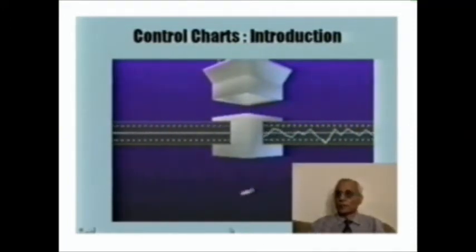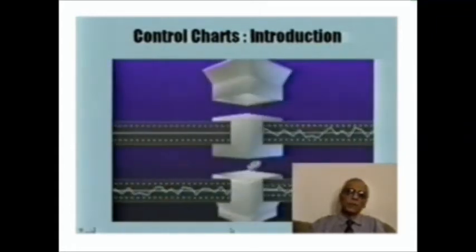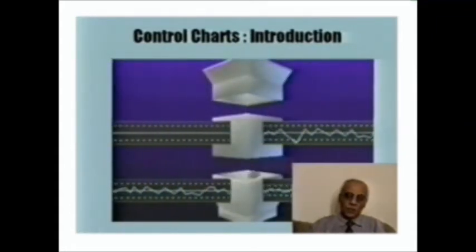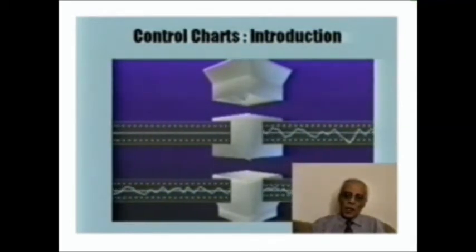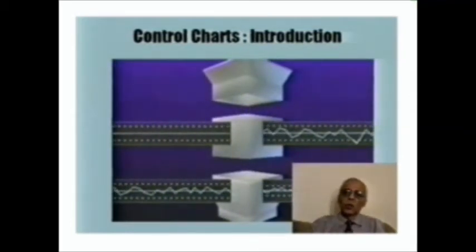A control chart concept simply means collection of data on a daily basis and determining what we call the data statistics, or the average of every day, or the range or the standard deviation, and then plotting these data or these statistics, whether it is the average or the standard deviation, on a daily basis, and establishing control limits, upper control limit, lower control limit, a center line.